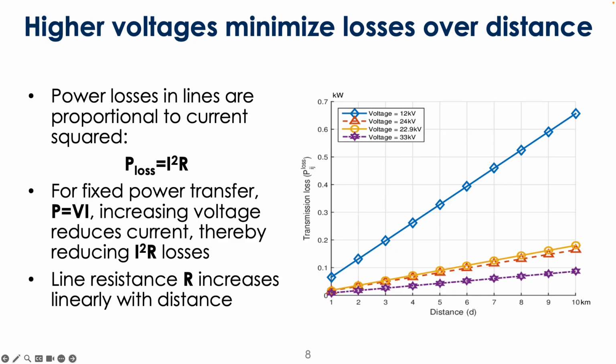Conversely, you could make that pipe bigger, reduce the voltage or pressure, and have the same amount of water coming out, but you'd have more passing through at any given moment. By doing this, you're reducing your I squared R losses because your I term goes down a lot.